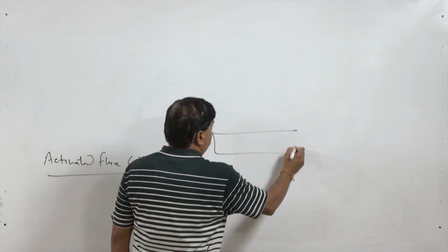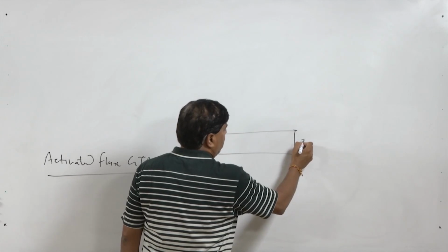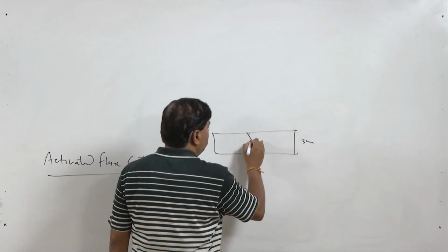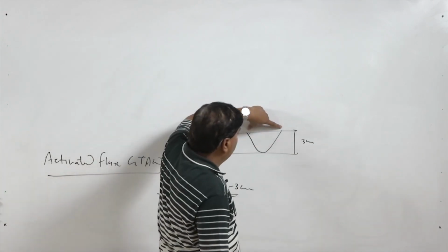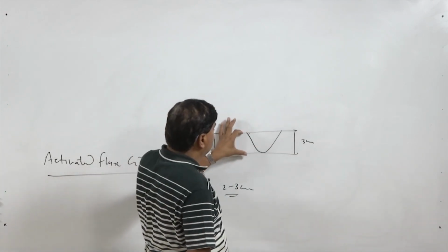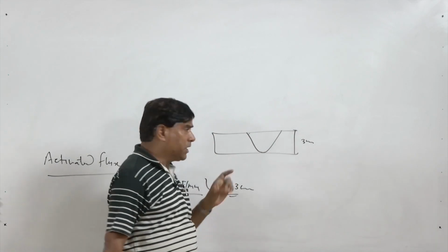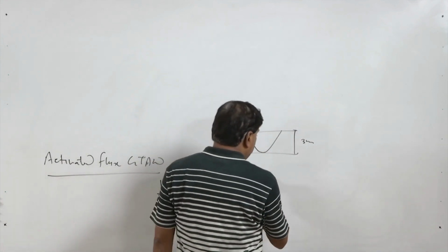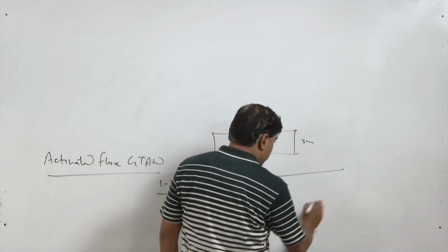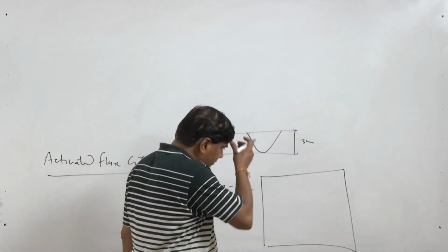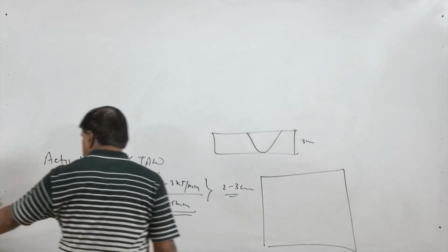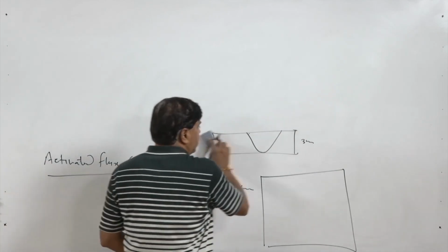Say this is a 3 mm thick plate; it may be able to melt through the thickness, with a wider weld bead width and somewhat lesser depth of penetration. But when the process is modified, the situation is just reversed.